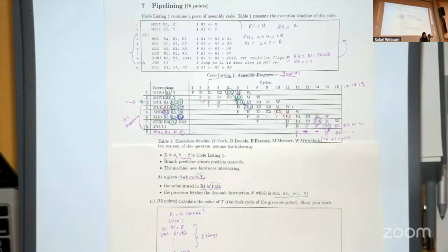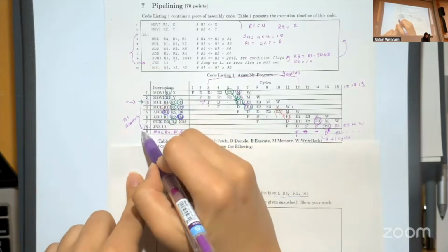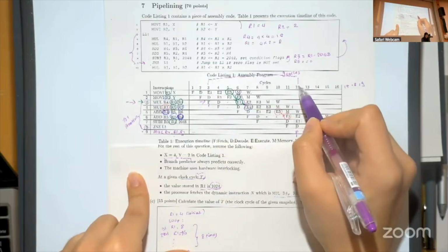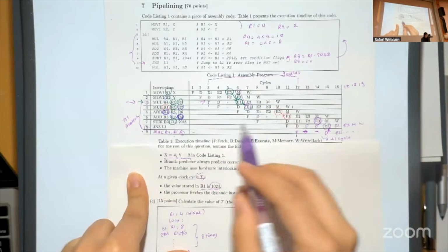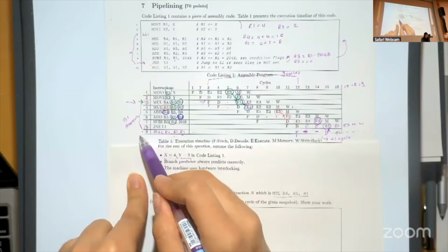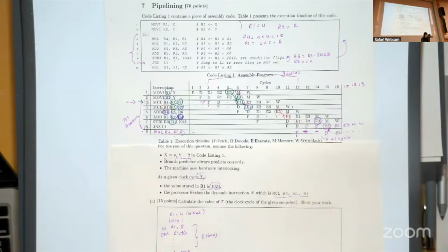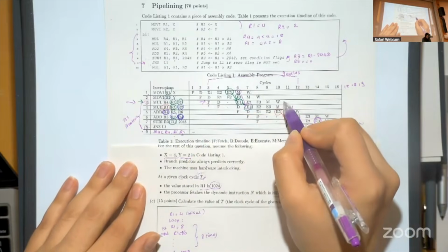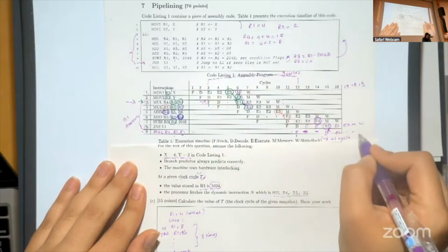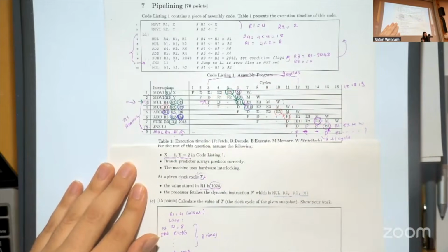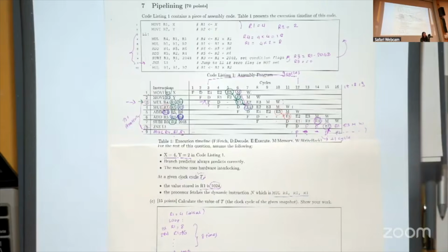Okay, so we first looked at the first iteration and then calculated how many cycles it takes. And then we checked the next iteration by starting at the instruction that is our snapshot instruction, to understand if something changes in the second iteration. And at this point, what we see is that the execution of the first iteration of this instruction and the next one differs because we have 1 more stall in the decode pipeline stage. So this is why the next iteration will have 1 extra cycle compared to the first iteration. Is that clear?